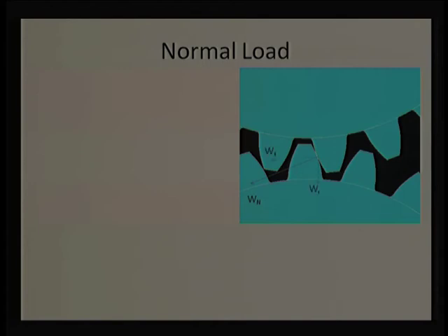We have some sort of pressure angle, and if I account for the pressure angle, I will get two components. We say Wt, the tangential component, which is going to drive the gear pair, and Wr, the radial load, which is going to push the gear away from the other gear, penalizing the bearing. So, there will be a radial load on the bearing.